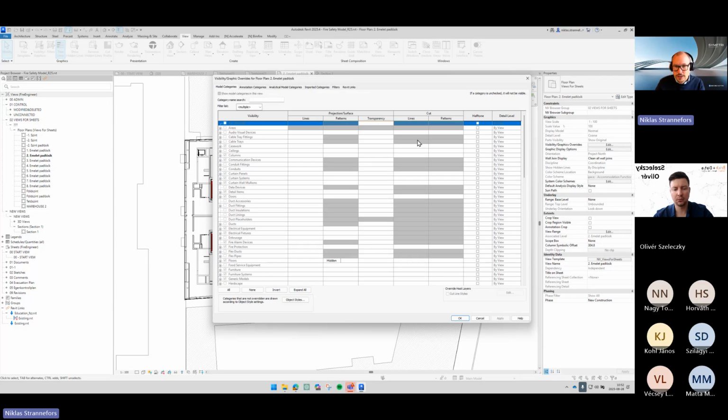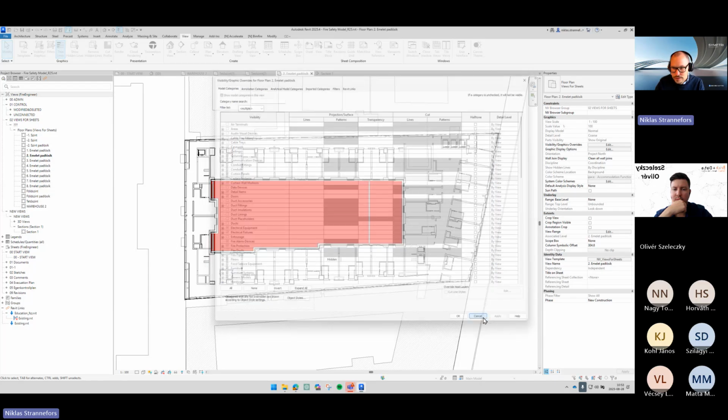And that's great because, as I mentioned, we're using view templates on these. View templates mean we say a certain number of views should look a certain way. We set a default, and it will change everything on them. So if we turn something on, it will show everywhere. If you turn something off, it will hide everywhere. I can do it from one place. Because it's gray, we can't change it here. We need to press Cancel.